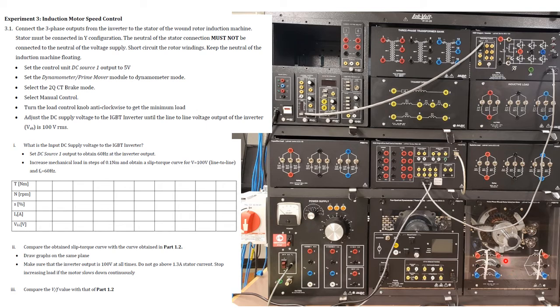You should just connect the 3 together, and this 3 as well. Then you need to measure 3 values: the DC voltage that you connected to the inverter, the line-to-line voltage, let's say VAB, and the DC voltage that you connected to AI, because you need it for switching.